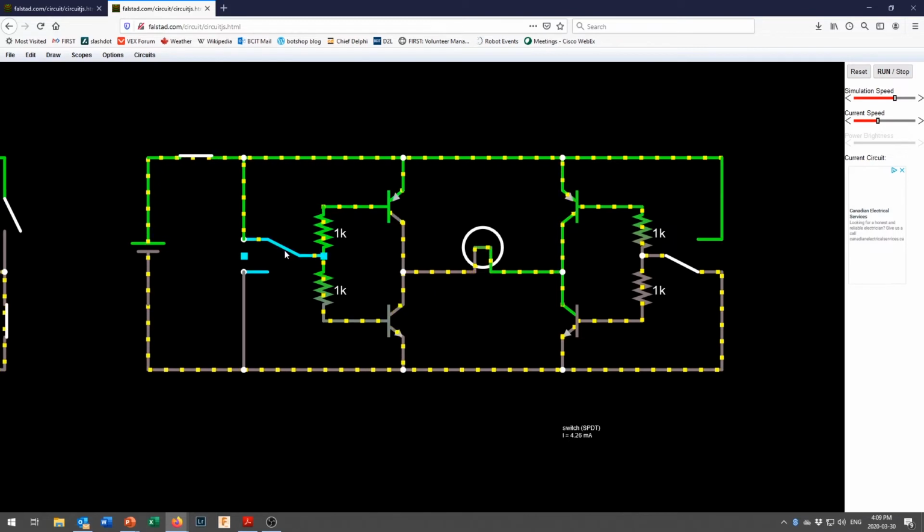So in this case, when I set this switch to go high right here, the high voltage comes down right here, passes through the two resistors. The high voltage turns off the PNP transistor, but turns on the NPN transistor. And if I swing the switch over right here, now this goes low, and this will turn on the PNP, because we've got electricity that can scoot out that way, which enables that one to flow. Just watch the arrow, and if it scoots out that way, then it's good to go through this way in much, much greater quantities. And down here, there's nothing coming through this way, so nothing can get through right there.